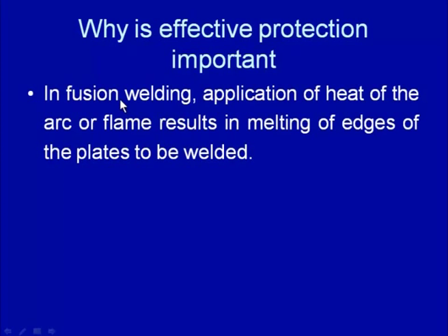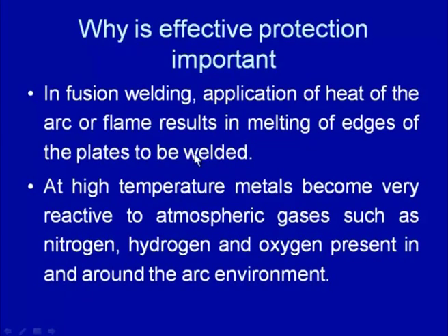Further, why should we protect the weld pool, especially in the fusion welding processes? Because we apply a lot of heat, either with the help of an arc or a suitable flame, to melt the faying surfaces. The molten metal from the faying surfaces in the weld pool, or the molten metal coming from the electrode tip after fusion of the electrode, becomes very active at high temperature to the atmospheric gases.